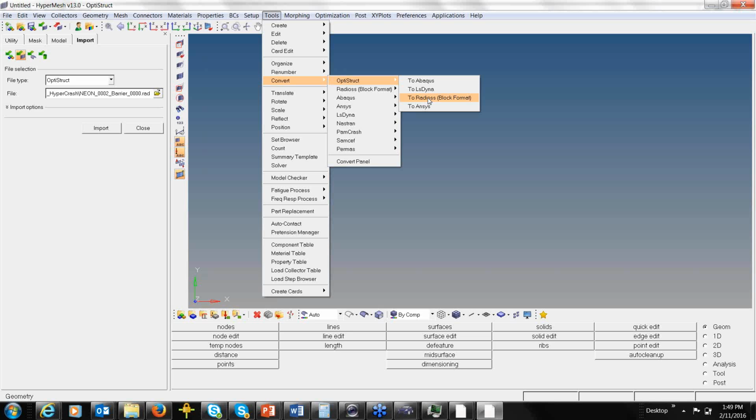Is there anything to look out for when you do that? Is there any OptiStruct type that might cause some problems? No, well, you have to check your material and make sure, because they're going from linear to non-linear material. You have to check those, but I don't foresee much, especially from OptiStruct to RADIOSS. Yeah, and going between the two equivalent solvers, the next thing would be that all the interfaces and things like that would have to be set up, since that is something you would not have in OptiStruct.